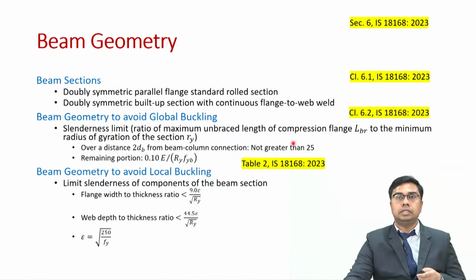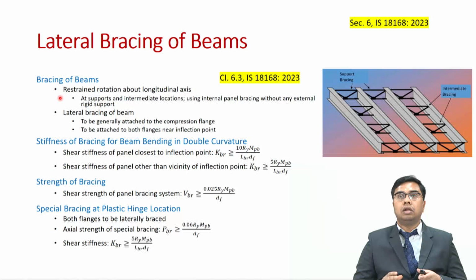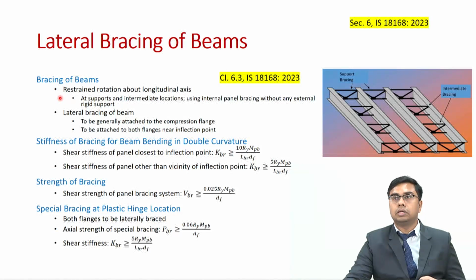So, you need to brace it. So, how will you do that? We need to restrain the rotation about the longitudinal axis at the supports as well as at intermediate locations using internal panel bracing without any external rigid support.